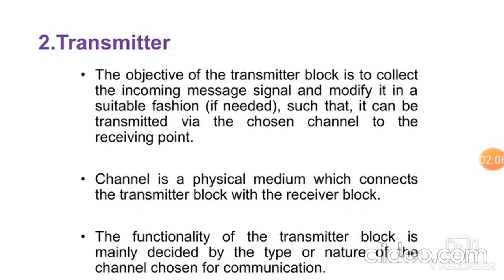In the case of analog communication, the information source is analog. In the case of digital communication, the information source produces a message signal which is not continuously varying with time; it should be in discrete form, in both time and amplitude, to be transmitted. Even a message containing text is discrete. An analog signal can be converted to a discrete signal by sampling and quantization. This all happens inside the transmitter.